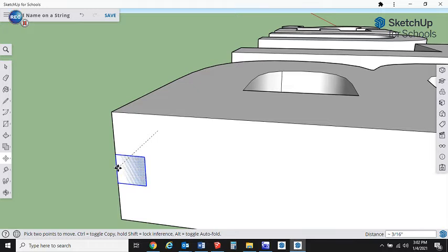We're going to drag it back over. You notice I didn't click though. I could click and then I could move it again, but if I just hover over that spot for a minute, you see how it's got the green dots? Well, that's just allowing us to line it up from that point. So from that point over, we are going to make this about 0.2, so it says in the book between 0.15 and 0.2 inches over.